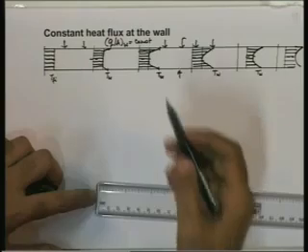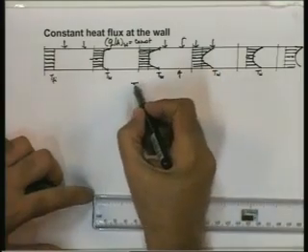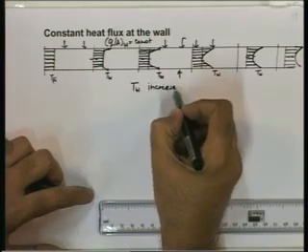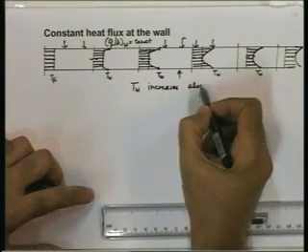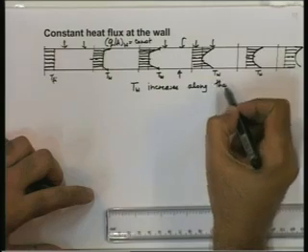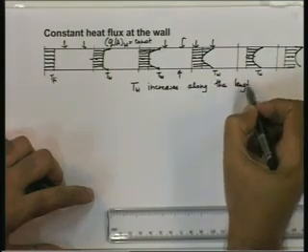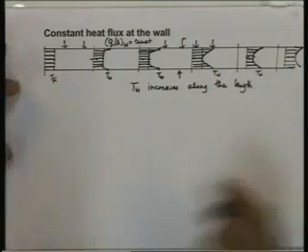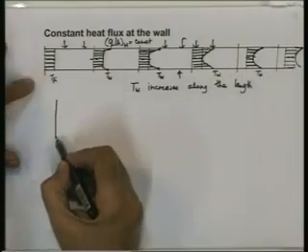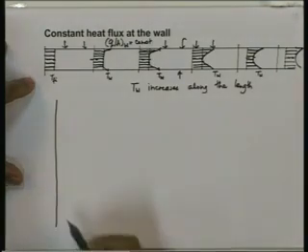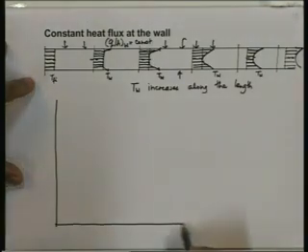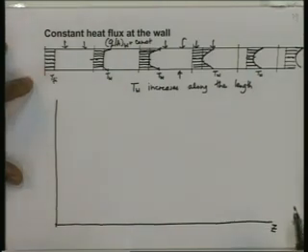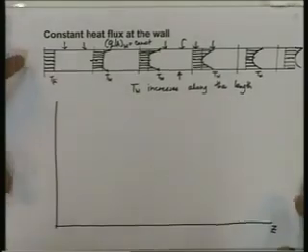So we notice that the wall temperature increases along the length, in the direction of flow. Again, let us sketch the fluid temperature profile, the wall temperature profile, and the heat transfer coefficient qualitatively.